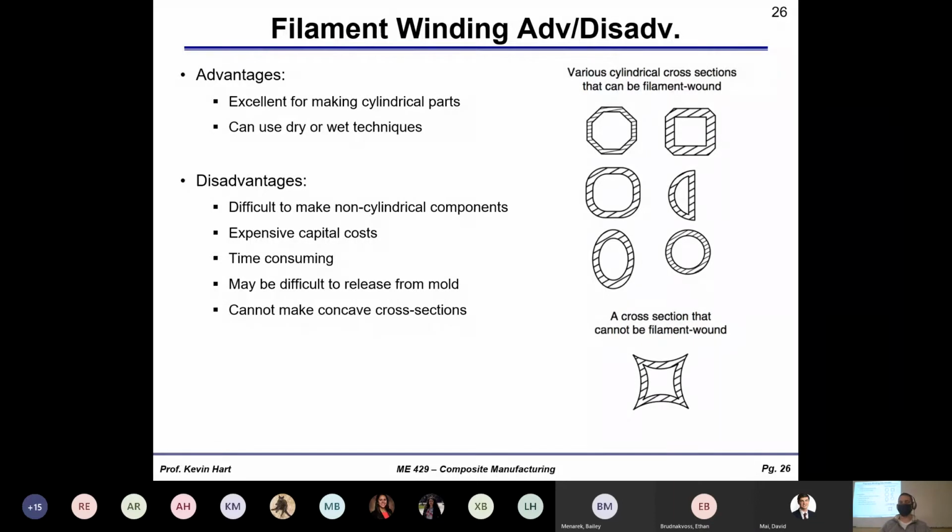No, I'm just kidding. Usually they'll have what are called collapsible molds, right? So the mold itself will be able to be collapsed. Maybe the mold is internally pressurized during the process, and then you take the pressure off. Think of a bladder system, all right? Maybe my mold is pressurized, and then when I'm done, I can take the pressure out, and my mold collapses, and I can work with my part that way. You might consider using a light foam mold, and then afterwards you just sacrifice the mold and say, well, I'm just going to machine off the mold and away I go, right?